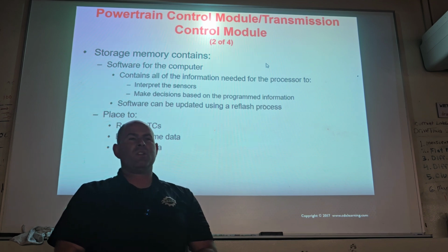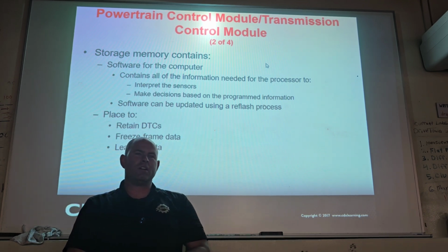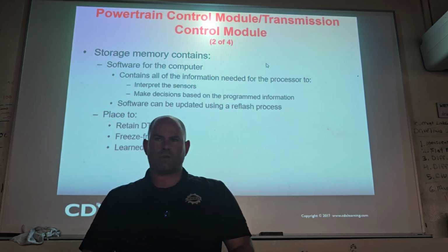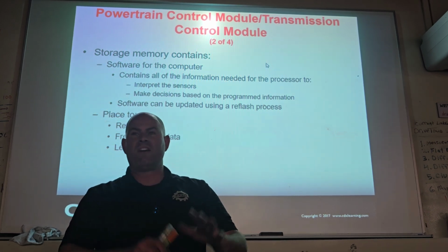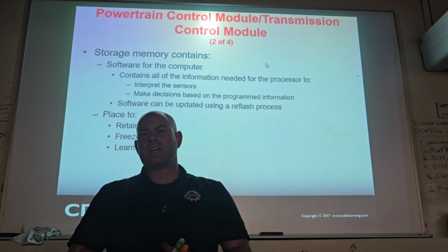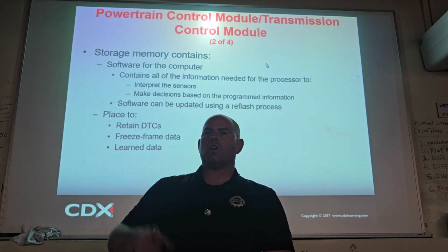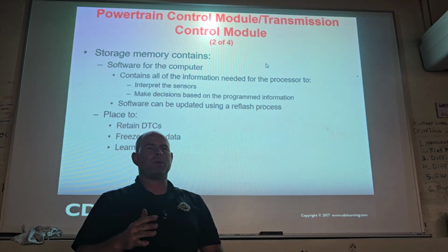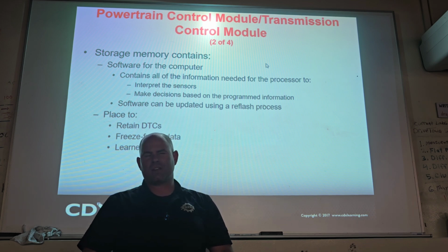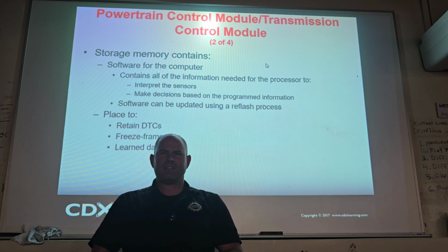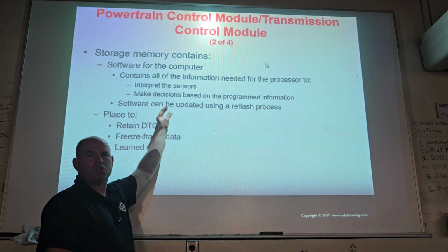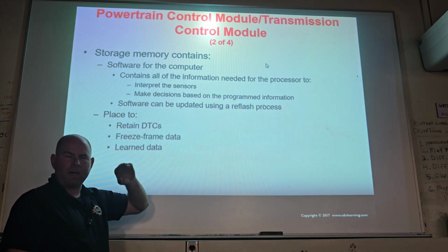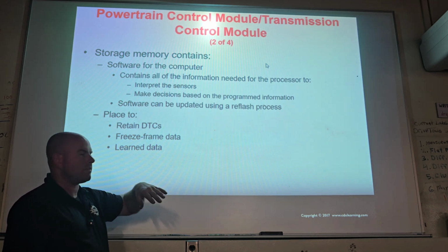Make sense? So if one of our steps is to duplicate the concern, I may stop and go to the customer and say, hey, you got a concern, I want to fix this for you, but I looked at your freeze frame and you were doing 147 miles an hour and everything on the car was hot. I can't duplicate that for you. Well, I want you to duplicate it. No problem. Let's start by filing a police report and then I'll duplicate it. You get the police to give me permission to drive it at 147. You know what I'm saying? Like, you could kind of play the game. But the point being, that's kind of a joke. The point being, if you want to duplicate an intermittent concern, get the freeze frame, and then you know how you should be driving it to maximize your chances of duplicating the intermittent.